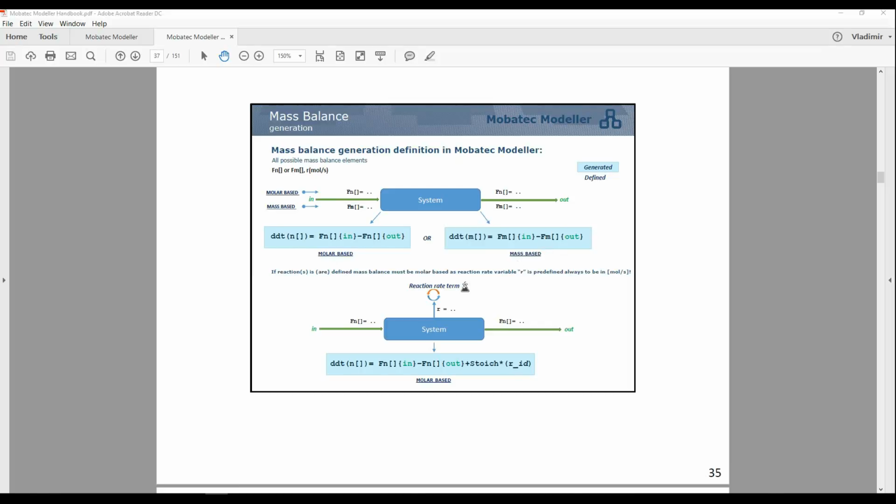Important thing to understand is that the balance equations will always be written in vector implicit form, and these square brackets, which are empty, are the sign of that, which means if you have n species, you will have one equation for species 1, then for the second species it will be 2, and for the nth species it will be accumulation of mass of the nth species equals nth species coming in minus nth species coming out.